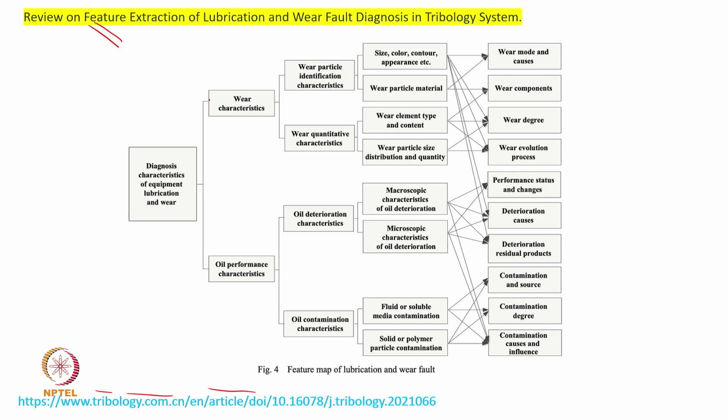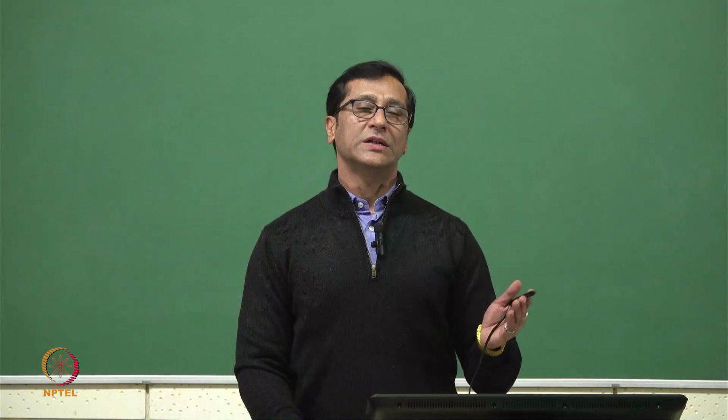I am just showing. They are using wear analysis and oil performance. In addition, we also look at vibration analysis, which is traditional. If you look at more papers and more books, they go ahead with vibration analysis. However, people say that vibration analysis comes as a later part. Wear analysis and oil analysis come first. So it doesn't matter to us, we want all three.